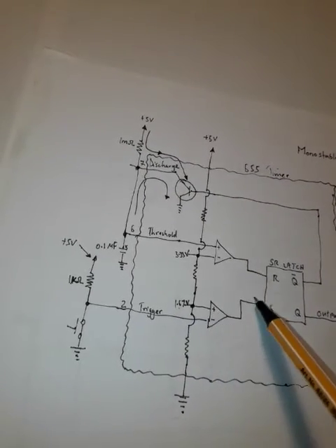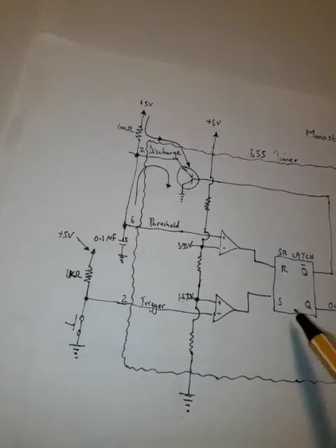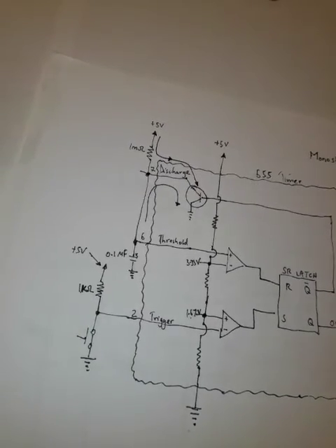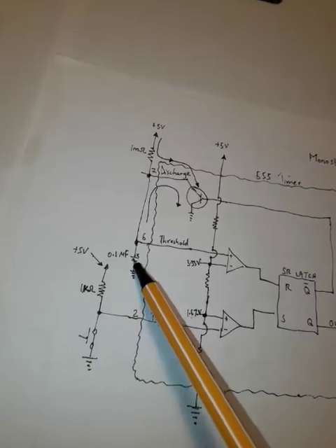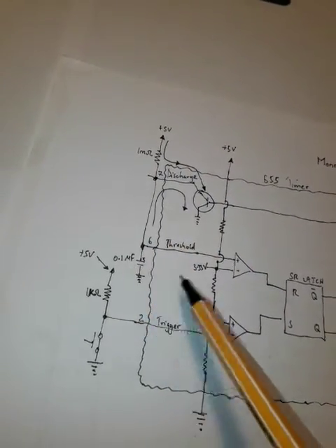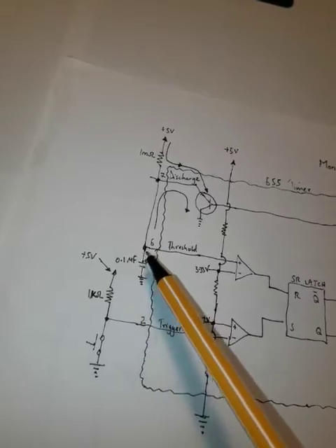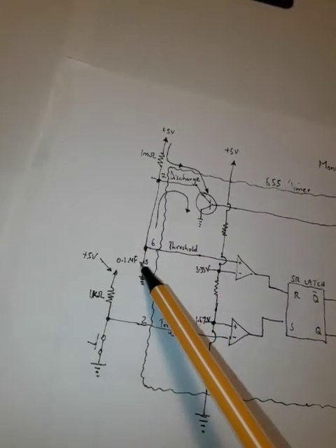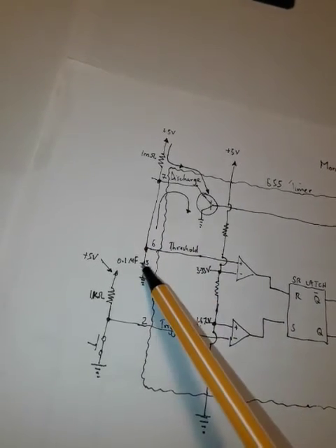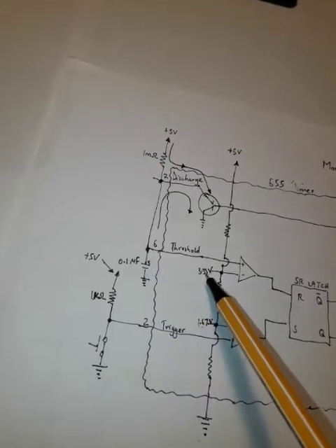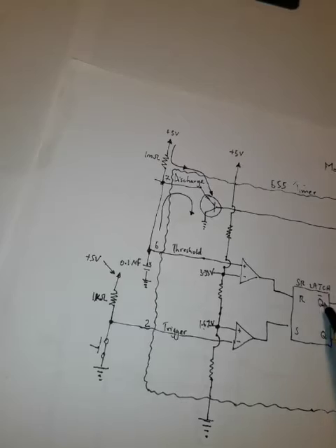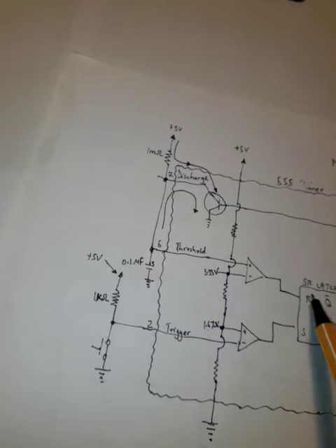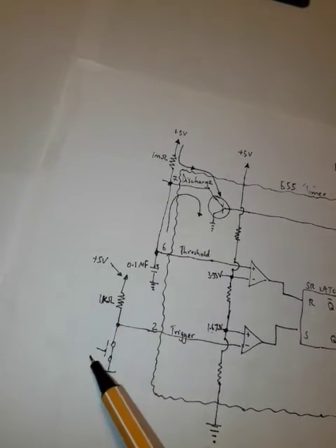And therefore, this comparator is going to set the SR latch. And then we're going to have an output. And this would remain this way because we have this capacitor here being charged. And while this is on, this capacitor is going to produce the charge required. Once this capacitor is charged above 3.3 volts, you have the reset set again, and it's draining the charge back.